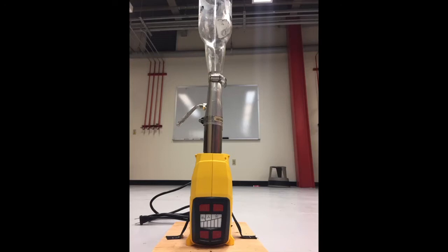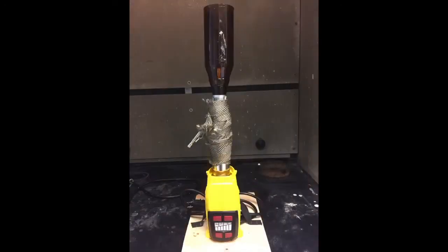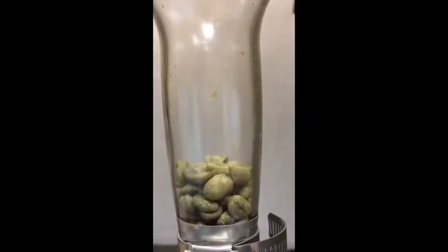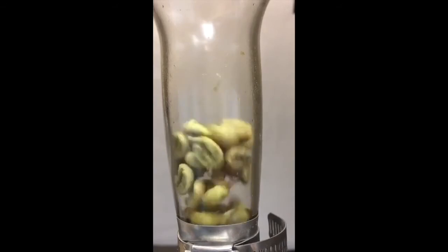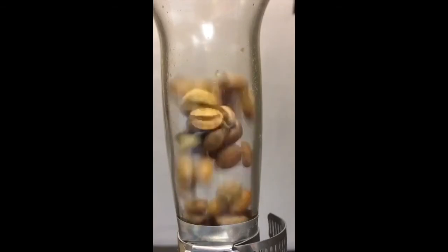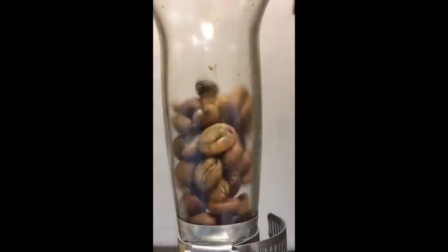However, without the metal casing, this now proved to be an insulation issue as well as a temperature issue. Thus, to eliminate that, the team wrapped the fluidized bed in insulation so as to protect both the team as well as keep heat in the fluidized bed. In addition to all the other parameters, the size of the bed was very important, so multiple bottles were used. Looking into experimental, we can see with a smaller bottle, thus a smaller diameter overall, the bed is more fluidized, thus showing that the beans will go further up into the column, which was an important consideration when looking into the flow rate.